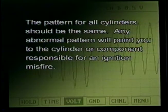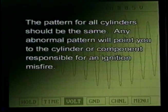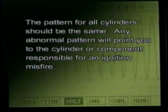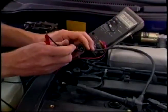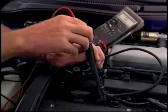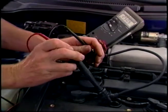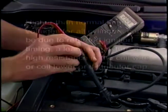The pattern for all cylinders should be the same. Any abnormal pattern will point you to the cylinder or component responsible for an ignition misfire. Uneven firing voltages between cylinders indicate problems with spark plug cables or a worn distributor cap, or a vacuum leak or open EGR valve that affects only one or two cylinders.